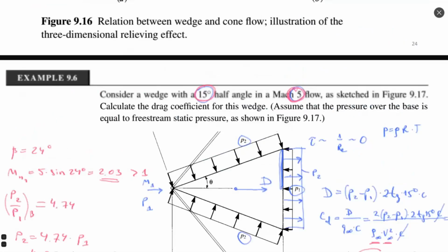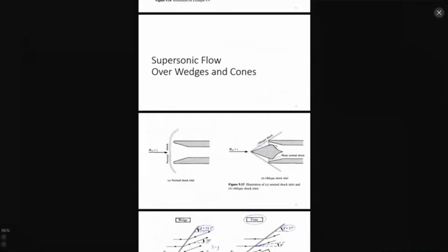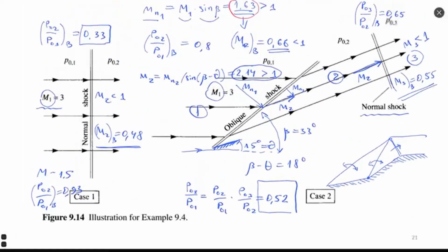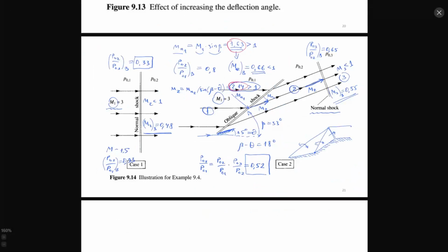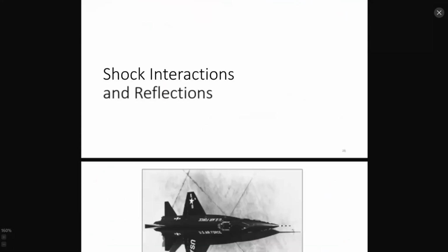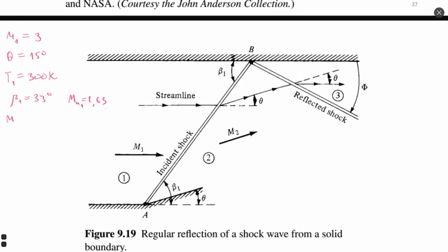And what else? The temperature ratio. And the temperature ratio I did not calculate in this example, so we will need to go and see it in Appendix B. Let me see. Mach 2 after this oblique shock wave is 2.14. M2 is 2.14. So you see how simple we made this example just using data from the previous calculation.